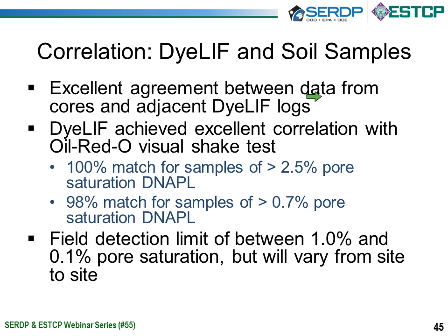So the correlation between DyeLIF and soil samples, getting to the conclusions: there was excellent agreement between the data from the cores and the adjacent DyeLIF logs. The DyeLIF achieved an excellent correlation with the oil red O visual shake test. There was a 100% match between the two for samples that were greater than 2.5% of the pore saturated with DNAPL, and we knew the saturations because we had done the analytical testing and petrophysical testing of the soil that we obtained from the soil borings.